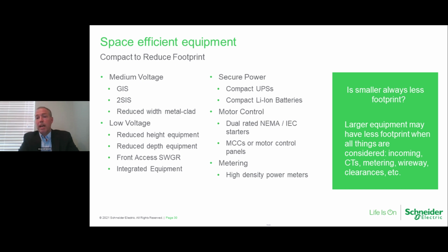I also like, having been hands-on early in my career, to look at it from the point of view of the guy that's going to have to work on the equipment 5 years down the road. I'm a big fan of our small footprint fusible disconnect switches, and it can be a great way to fit additional capacity into a small space.